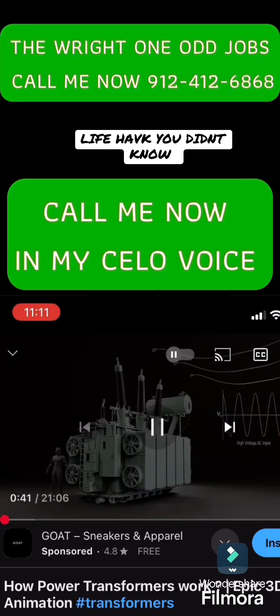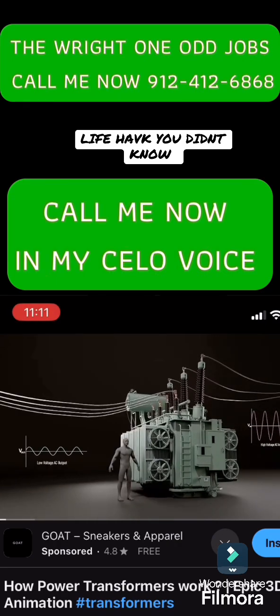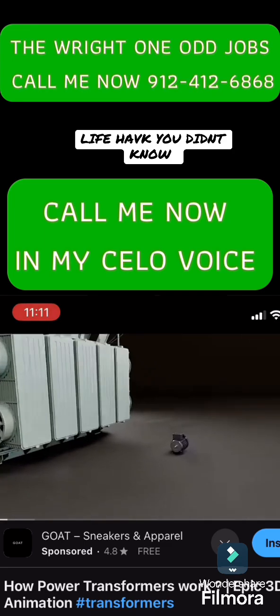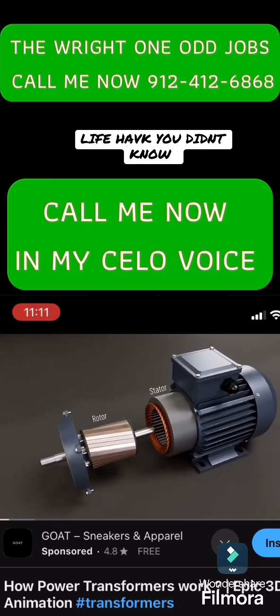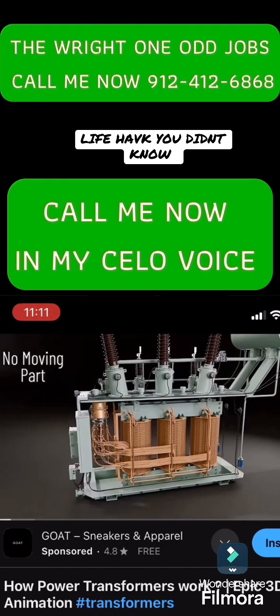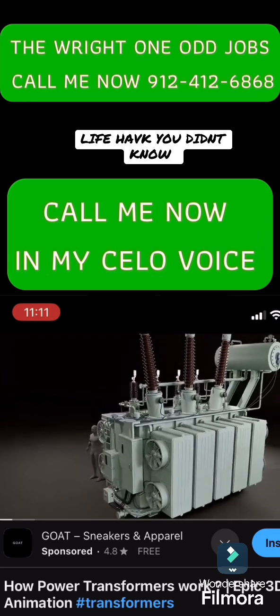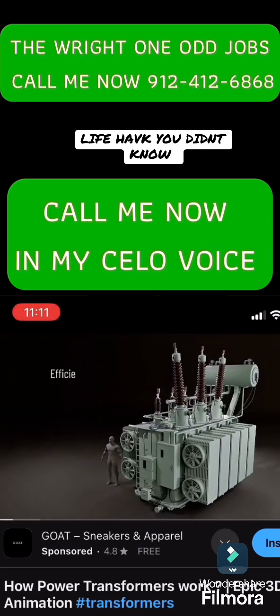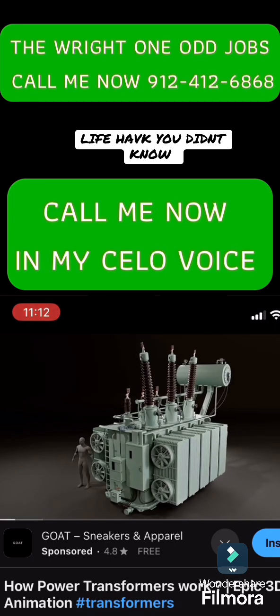A transformer is used for increasing or decreasing the voltage levels of an AC supply, with a corresponding increase or decrease in current. It is a static machine, which means, unlike an electric motor, which has a stationary part called the stator and a moving part known as the rotor, a transformer does not have any moving parts, except for the OLTC and motor drive unit, which we will discuss later in this video. Due to having no moving parts, transformers do not incur any frictional or windage losses, making them one of the most efficient electrical machines.